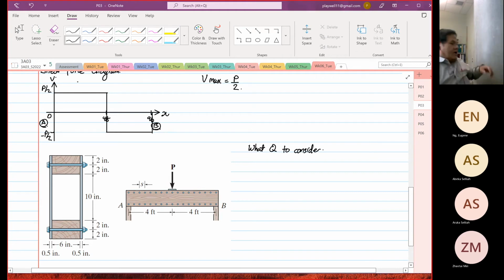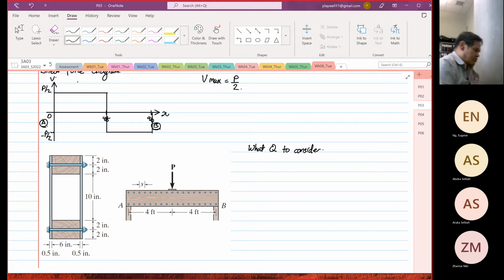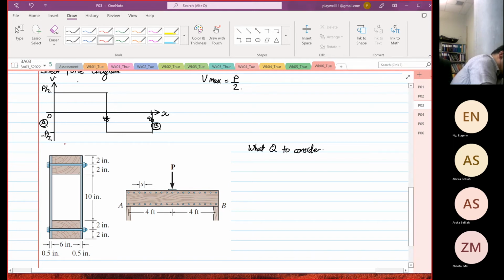Now this is the part that requires failure analysis. Watch here. So we know that we have a shear force, which is our Vy coming down. Vy will generate a shear flow, right? We know that the shear flow, one will go to the left and one will go to the right.